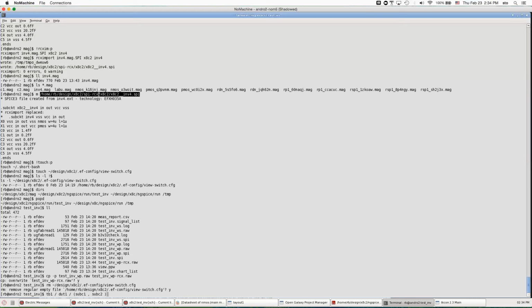And another question, in your opinion, if I'm supposed to get this RCX extracted view, get it into Electric, and create a test bench around it as a designer. Now, the fact that I have a minimum C and minimum R in this RCX extraction. What's the minimum threshold for R and C for which the RCX extraction tool would have these series resistances and capacitances modeled based on the layout view?